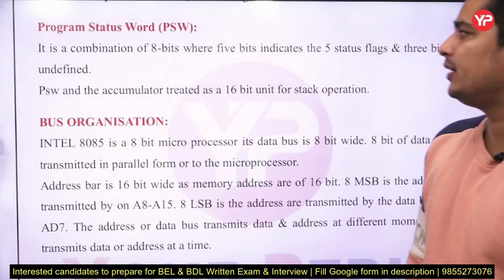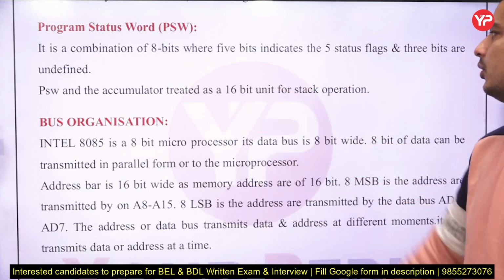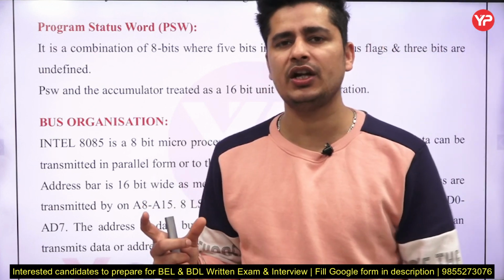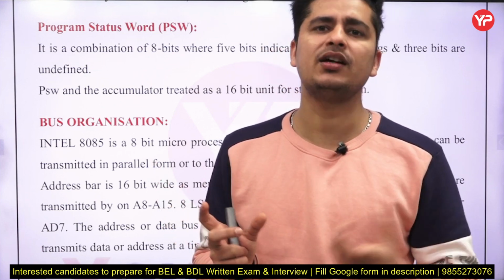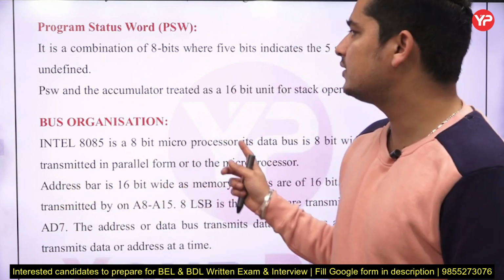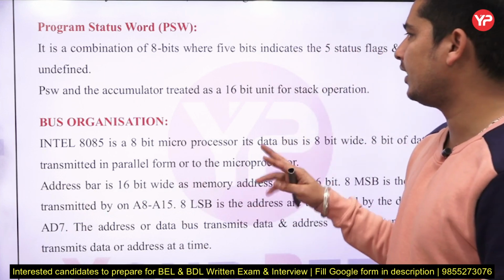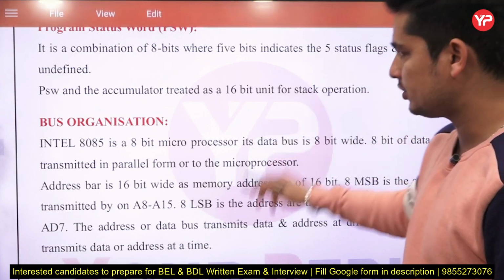So inside this 16-bit unit, you can check the status of 5 flags and the result. From that result and status of flags you can tell whether the result is positive, negative, 0 or like that, every information. That's why this is called program status word. Program status word and accumulator we can treat as a 16-bit unit for stack operation, right?